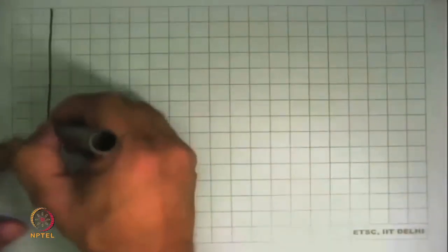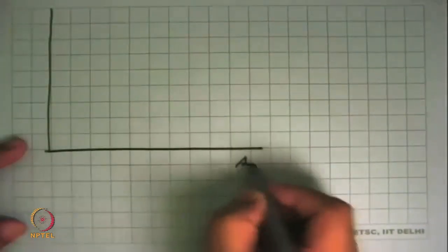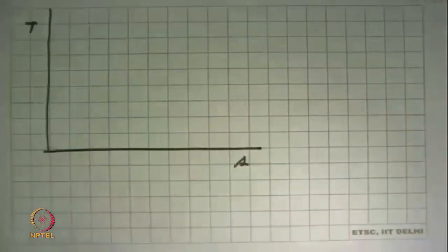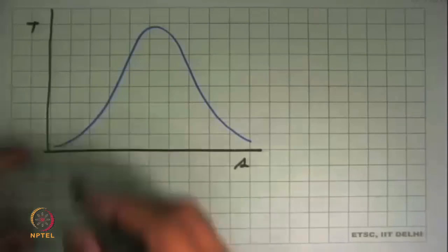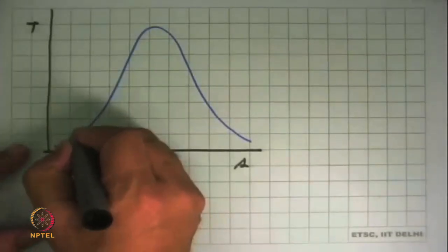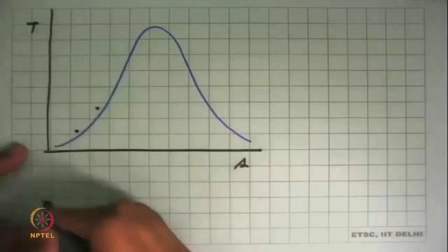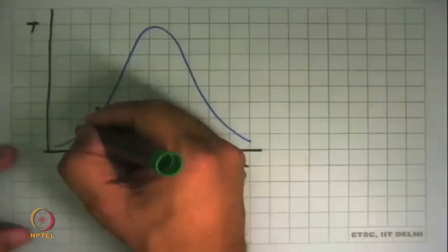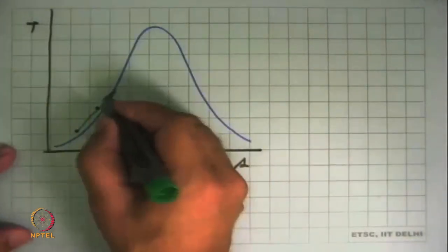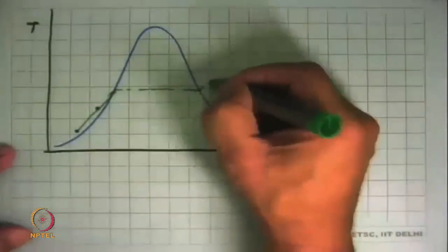Okay, there are two examples of mixing that I have given. The one thing that we will look at, okay, we see what happens on the property diagrams. And I will draw the case of say the deaerator. That's the saturation dome, and what we have is compressed liquid coming from here, heated up to this point, and if nothing would have been done, this is constant pressure heating, so this line will go off there, and then it will go there, and then this will go there.